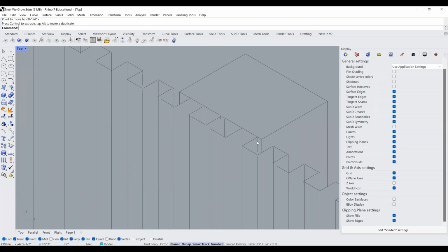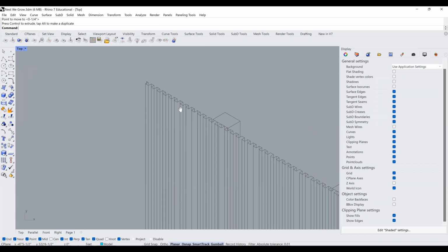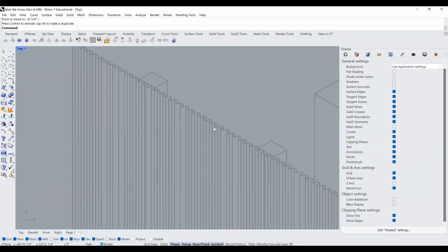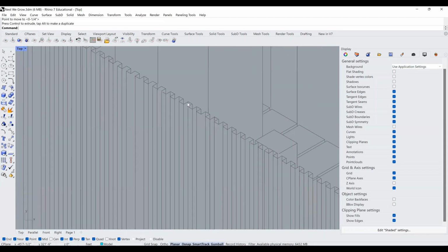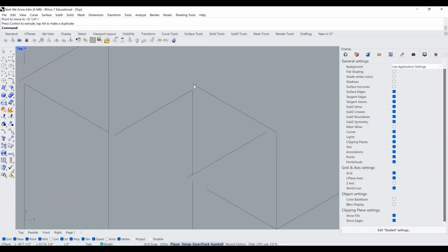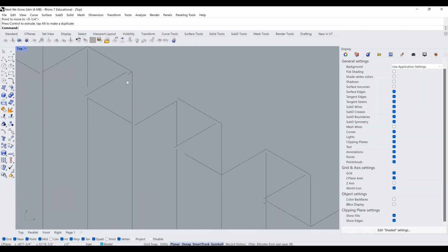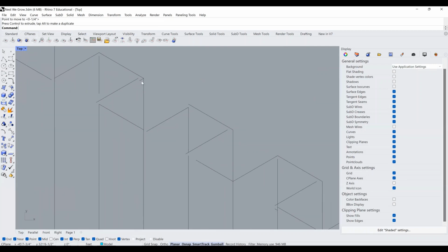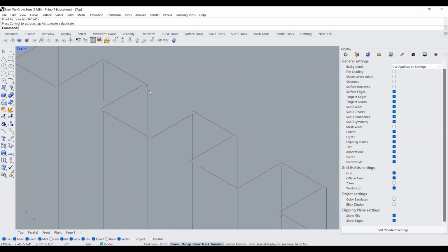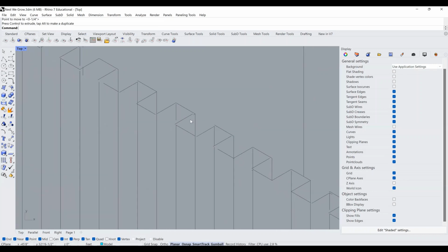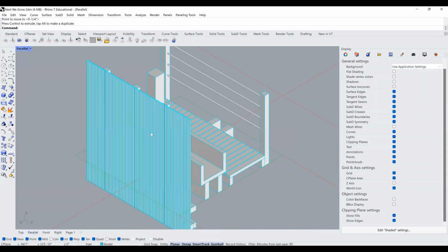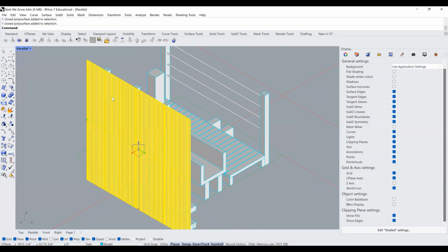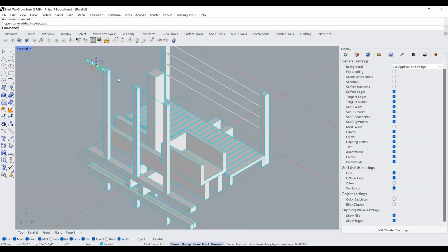And I think one thing that is going to be helpful for this part, because it's a very tiny part, is that this, as you can see here, is supposed to have a thickness. But if you draw this out in Rhino and export into a PDF, it's going to be super dense, and it's going to appear as a thicker line width than it's supposed to be. So for clarity, I am going to delete these and just make this without a thickness.